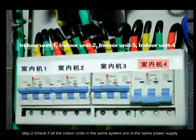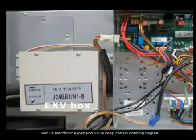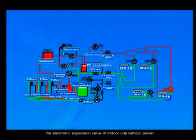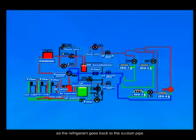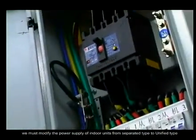Step 2. Check if all the indoor units in the same system are in the same power supply. If there are any indoor units without power and its electronic expansion valve keeps certain opening degree, in this case, much liquid refrigerant go through the electronic expansion valve of indoor unit without power, and the refrigerant doesn't evaporate and absorb heat from indoor side. So, the refrigerant goes back to the suction pipe of outdoor unit in the same power supply. If there are problems as above, we must modify the power supply of indoor units from separate type to unified type.